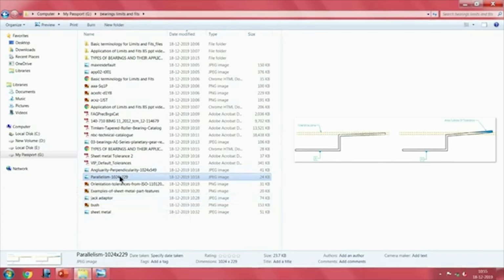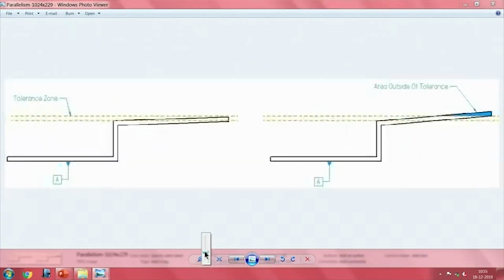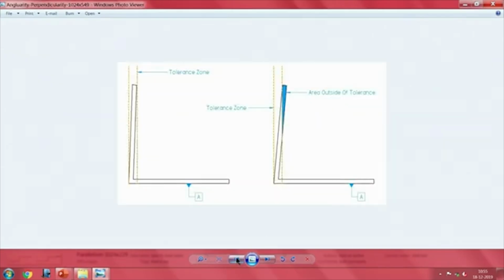Now, especially in the case of sheet metal, ISO has spent huge amounts of effort in documenting it. Strictly speaking, something falls in the tolerance zone, and then this is above the tolerance zone. Imagine one end of it falls within here, another end falls here. Now do we accept the part or not? That is where things like parallelism and other features are presented very well here.